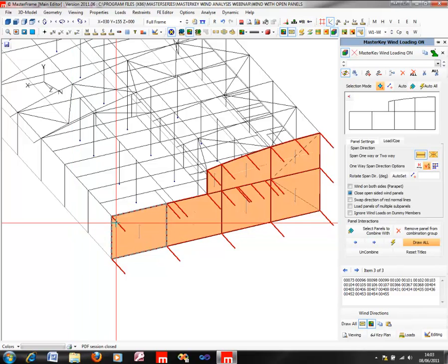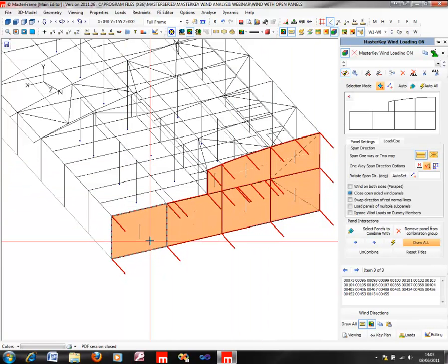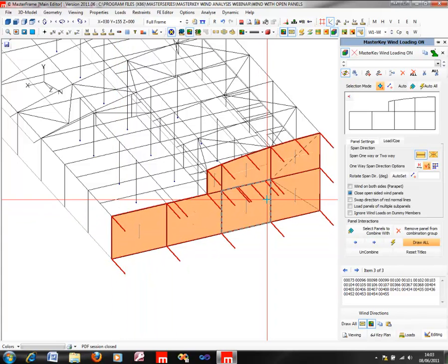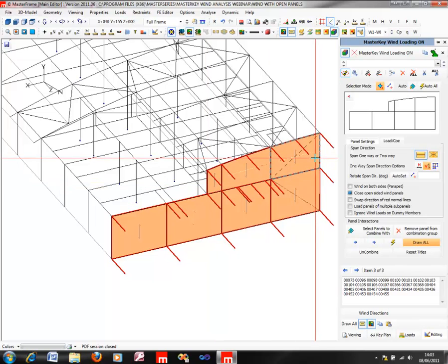Naturally, we know to the code, the 6399, that we get higher wind pressures on the leading wind edges, so we might start off with a zone A going to a zone B, maybe all the way back to a zone D at this side. With this surface as one entire surface, the zone A will start at the leading wind edge of the surface and go all the way back to a zone D. So when we get to here, actually we might be in a zone B or something like that, and this would be a zone B throughout the entire height. Whereas in actual fact we might like to start off with the new leading wind edge for this portion, going from zone A all the way back to zone maybe B or however far it might extend.